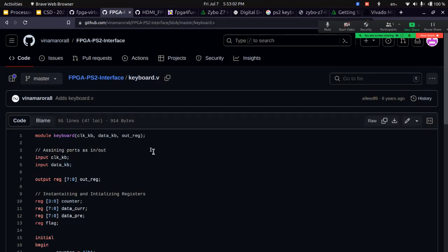So interrupt has higher priority. As soon as an interrupt comes, the fetch cycle will jump to the interrupt location. So you'll have two fetches. In the first fetch, you'll detect the interrupt, and in the next fetch, you'll go fetching the instruction of the interrupt handler. So this is how you do the keyboard, and how to read this keyboard.